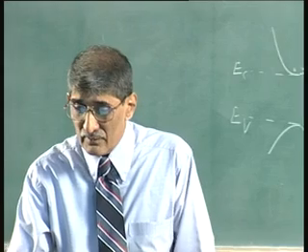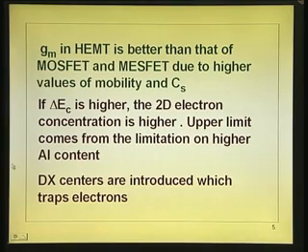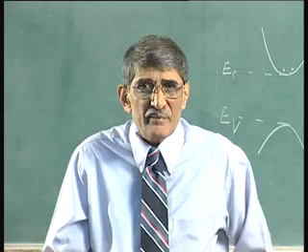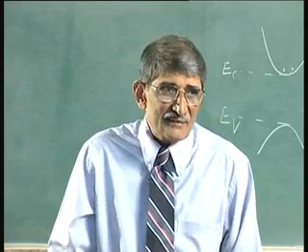But there is an upper limit because higher aluminum content introduces some trap levels which actually affects the total performance of the device. The trap levels will be present in that layer and they trap some of these electrons without releasing them to the channel itself. The electrons are trapped there, they are not available to the channel. So, even if you increase, there is no benefit. You may say, okay, I will still tolerate that, but it gives rise to poor performance at lower temperatures, because more trapping takes place.